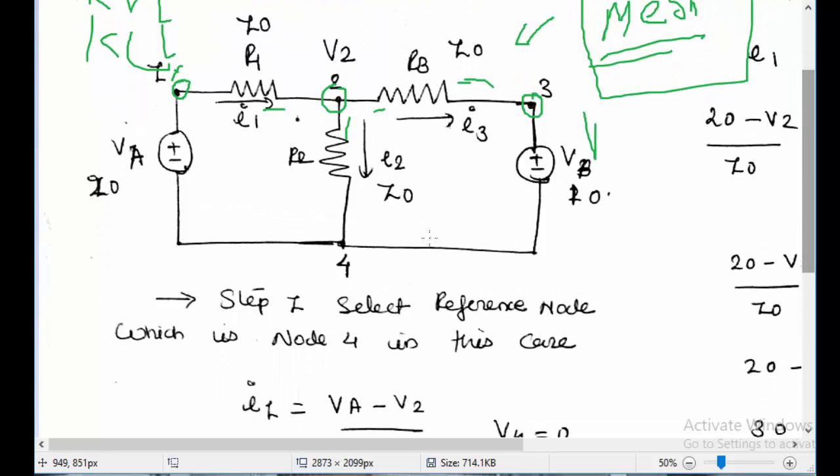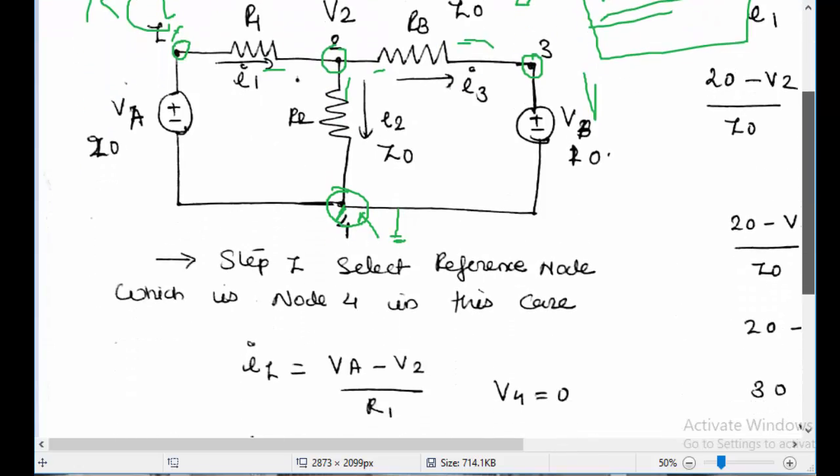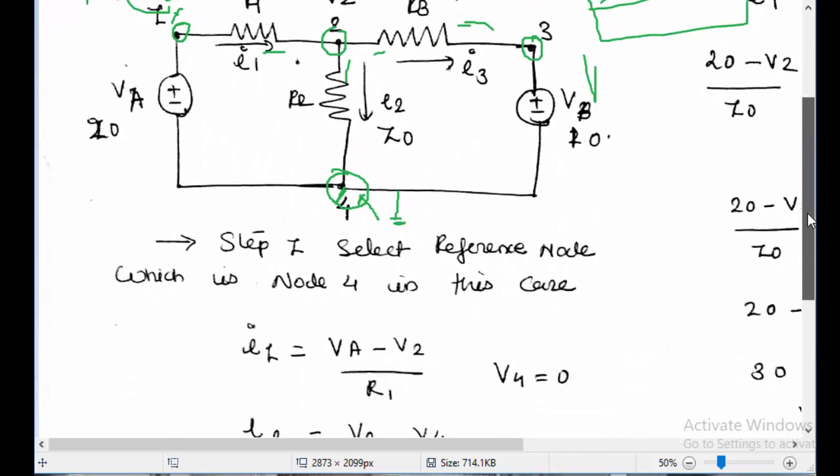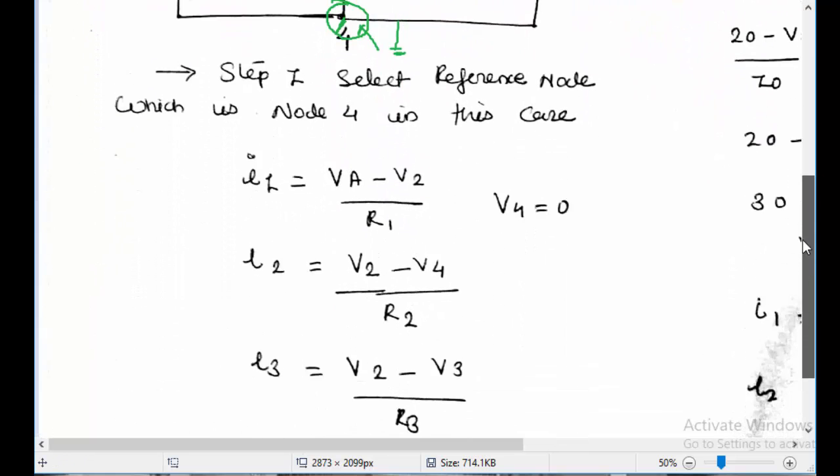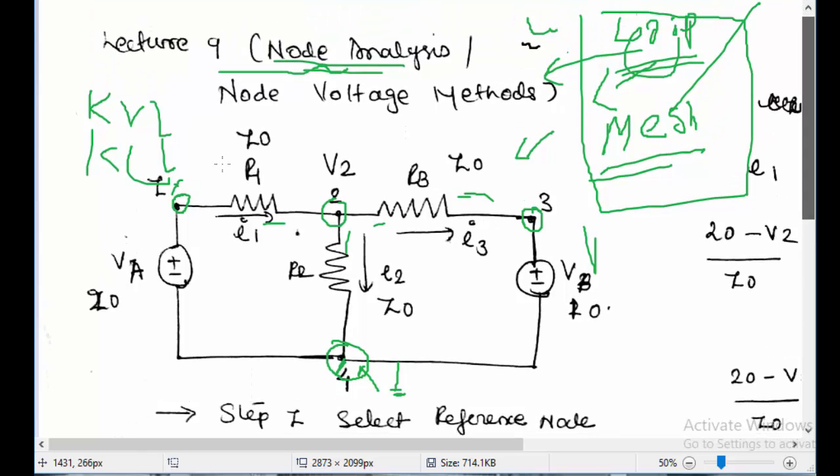And you will need one more node, which is known as a common node, and this node is usually connected to the ground or the earthing, and all the nodes are having a common node. So this is a usual circuit, and this can be solved using the node method. So we will use this circuit in this example by applying the node voltage method.